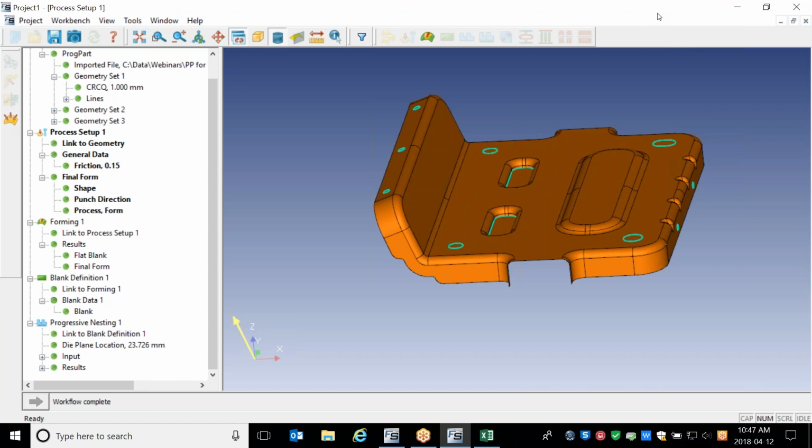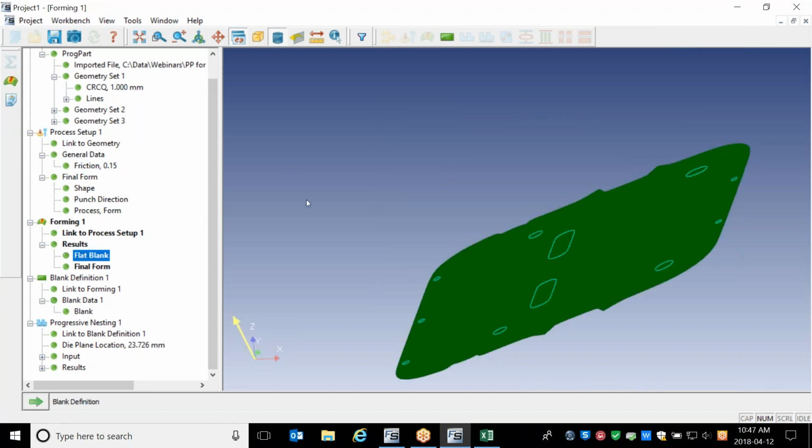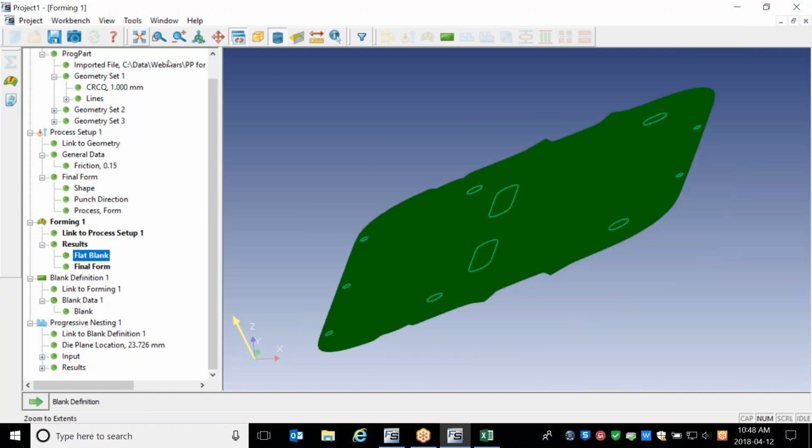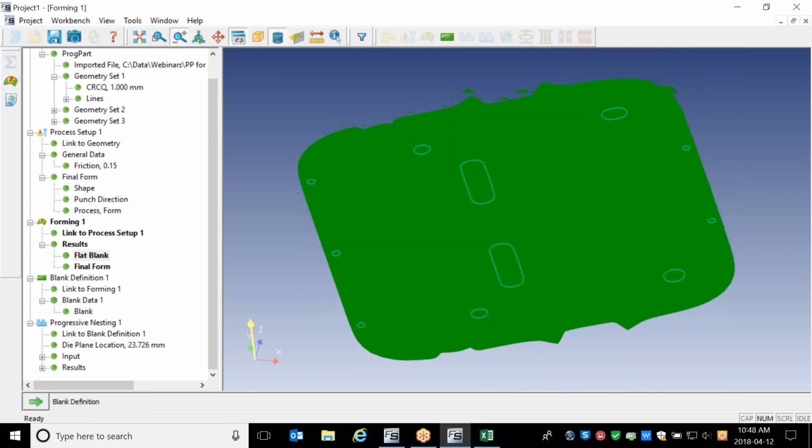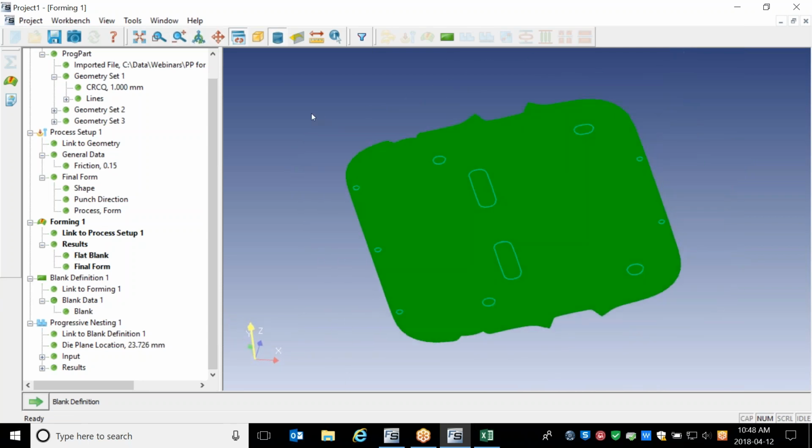Okay, and then the second question is related to the unfold. Typically, the issue with forming simulation software for sheet metal is that your unfold will tell you your trouble spots, in terms of the thinning that can occur. Do you have forward incremental simulation that actually shows the stresses going through the die as the part's processed, as opposed to the one-step unfold? Yes, we do, in the process planning software. And if that's another session, that's fine. We'll get that information. I just want to know if the software is capable of it. Yes, it is capable.